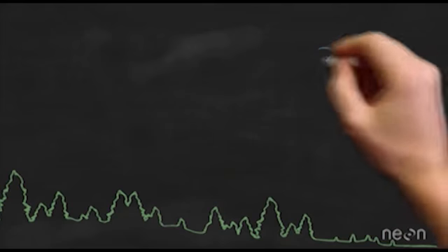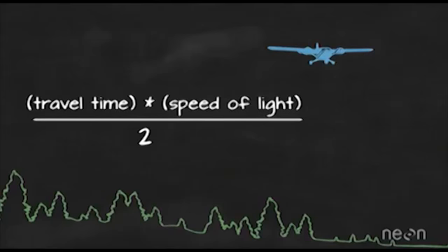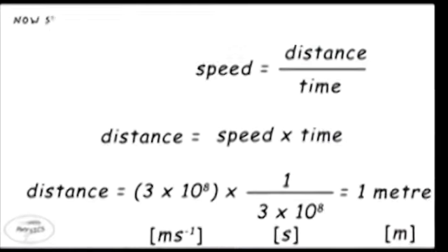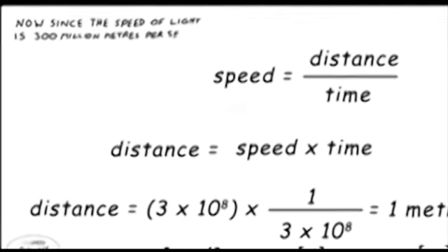As light touches the surface of an object, that light will be bounced back to its origin, and by measuring the time needed for the light to travel from the sensor to the object and back to the sensor, LiDAR can measure the distance to the object. But because light travels at an amazing speed, the interval between the transmission and the receiving event happens in a very short time, in the order of picoseconds.